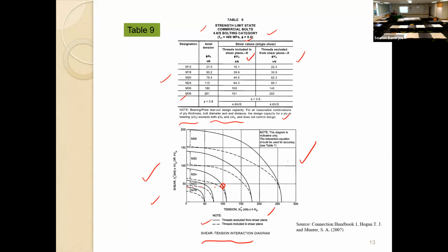Remember, while applying the shear-tension interaction diagram, it is important that you ensure that the bolt is safe in carrying the shear and the bolt is also safe in carrying the tension. Only then can you use the interaction diagram.